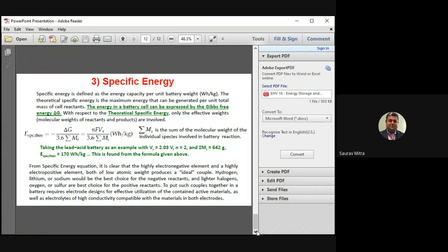So this is the difference between specific energy and specific power. High specific energy means continuously over time it will give you steady high energy throughout the driving operation. But when I say specific power is high, it will be used only for a very small time frame, and it will give you bumper energy. Bumper energy means it will play for 3 overs and generate 40 runs, or it will run for 10 minutes and help you to climb the hill.